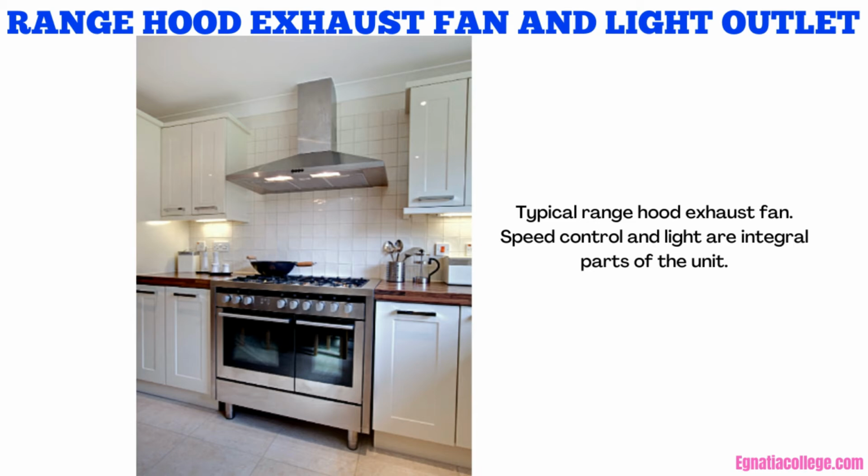Homes heated electrically with resistance-type baseboard units usually have excess humidity. These heating units neither add nor remove moisture from the air. The proper use of weather stripping, storm doors, storm windows, and a vapor barrier of polyethylene plastic film tends to retain humidity. Vapor barriers are installed to keep moisture out of the insulation. This protection normally is installed on the warm side of ceilings, walls, and floors, under concrete slabs poured directly on the ground, and as a ground cover in crawl spaces.